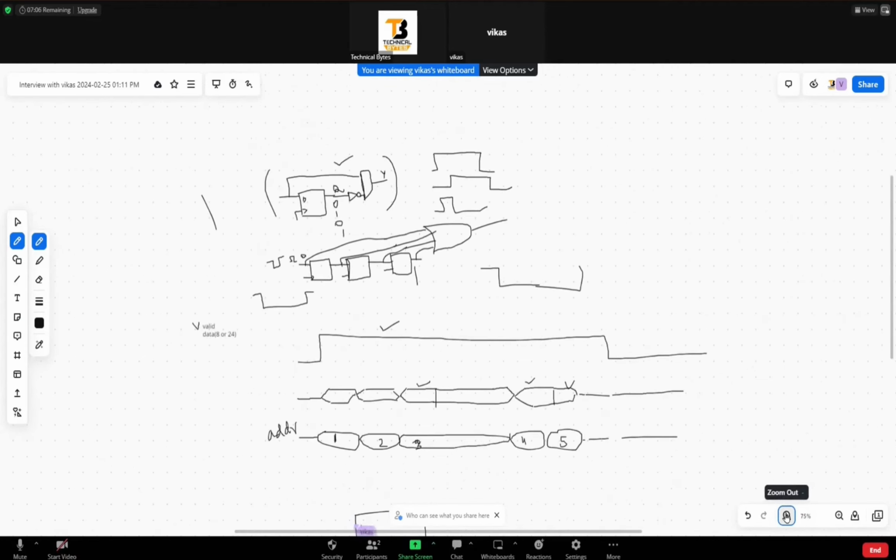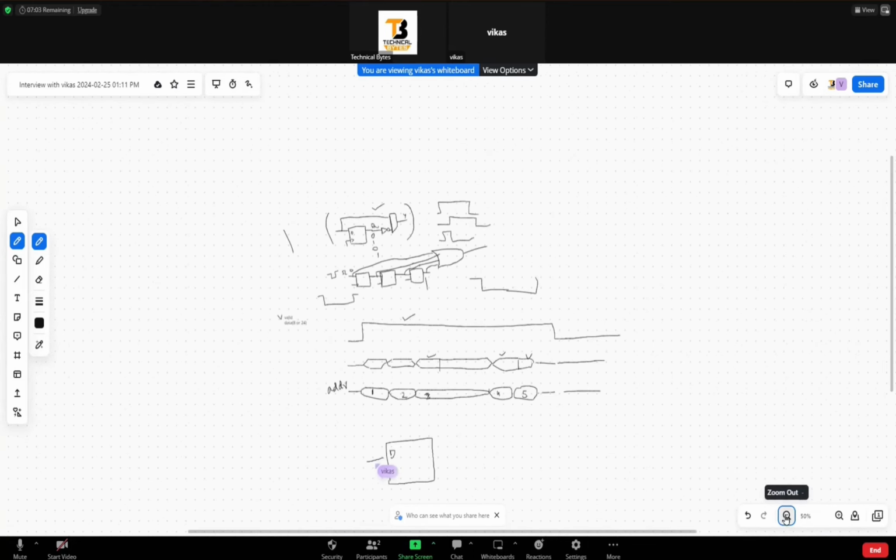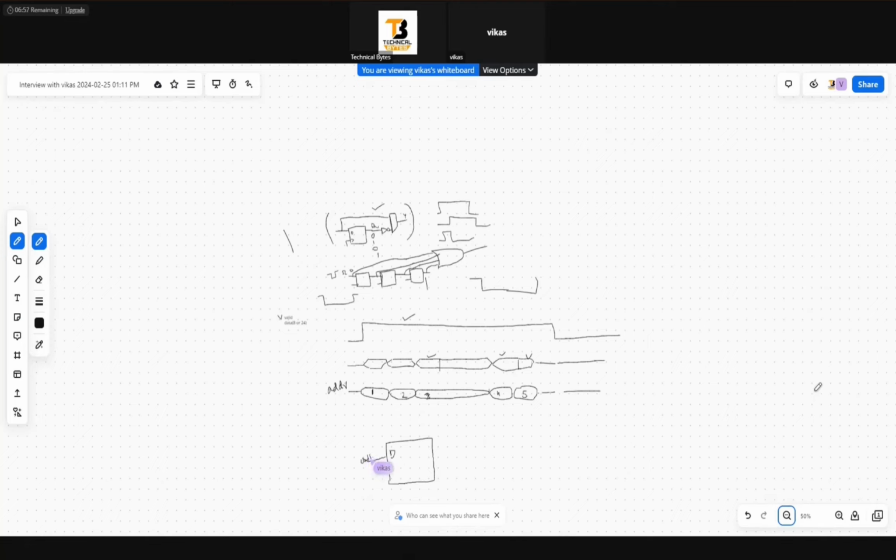So this will be a multi-bit flop where I'll be registering this address. Of how many bits it is, no problem. So this will be our registered address, and I will be having a valid signal also. This is clock, and for this clock, I will keep an enable signal as this valid. So whenever valid is there, we will be registering this address in this flip flop.